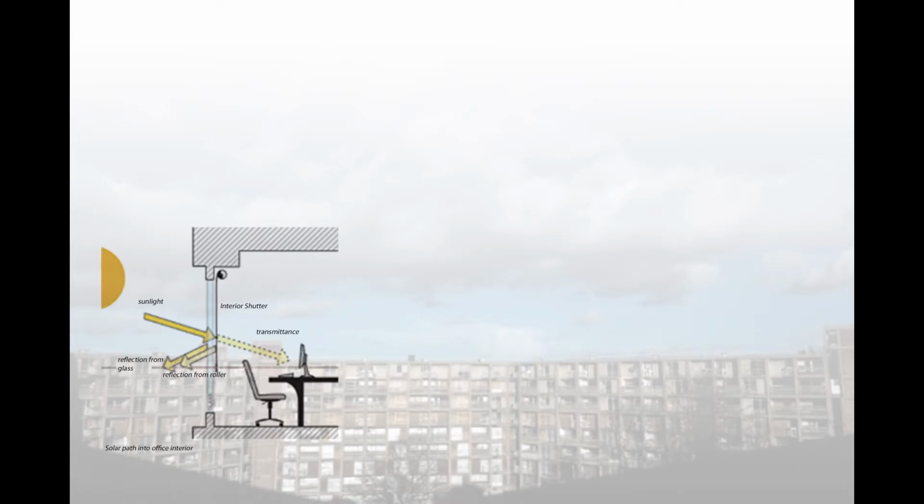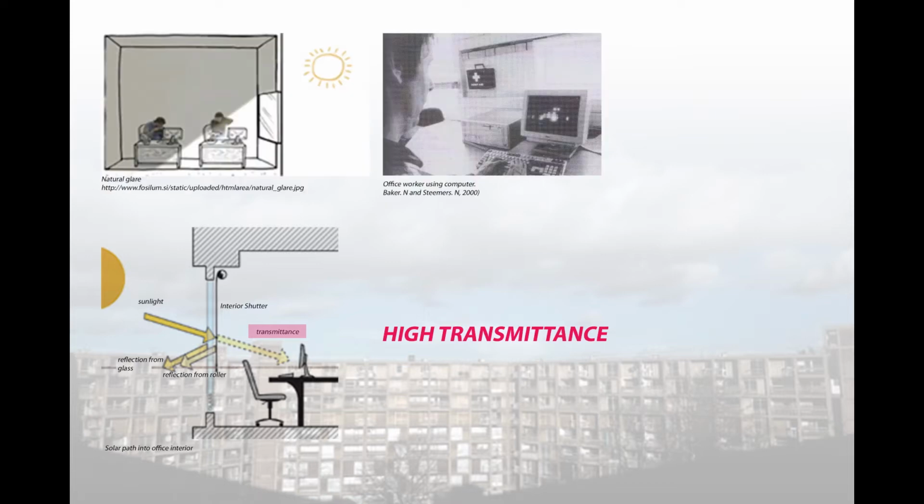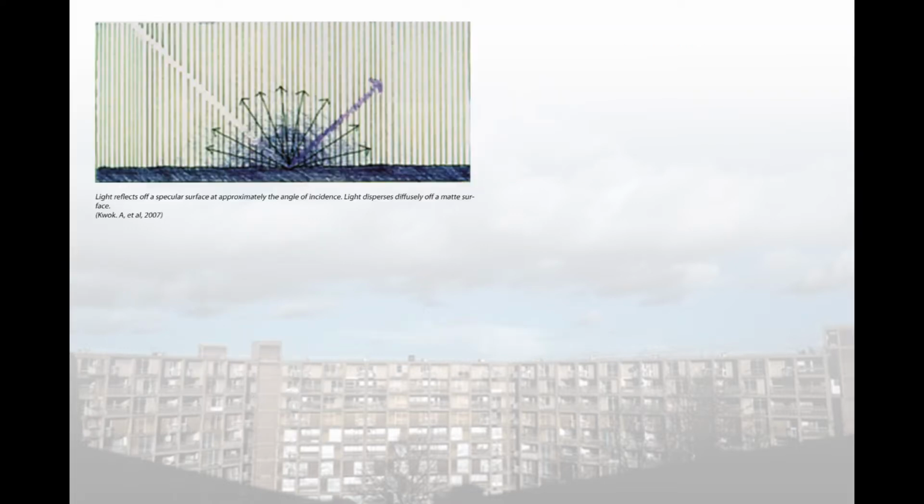Note that fabric with high transmittance may become very bright when the sun is on it. This causes unwanted glare and problems for the unfortunate people operating computer screens inside the room. In such situations, CIBSE recommend a transmittance of less than 0.1 for shading fabric, and the room must have luminance of a minimum of 500 lux.